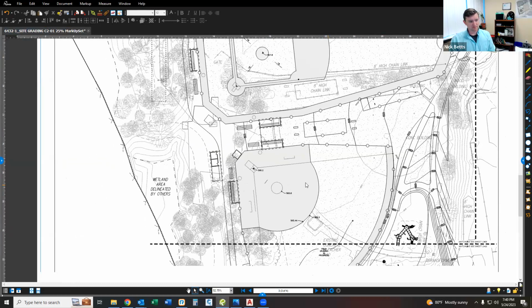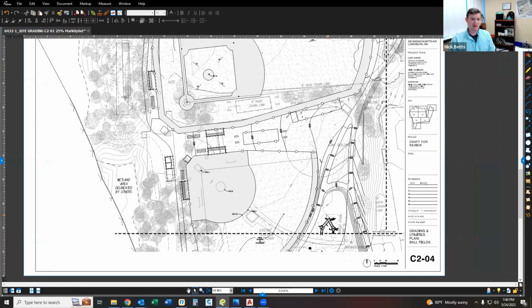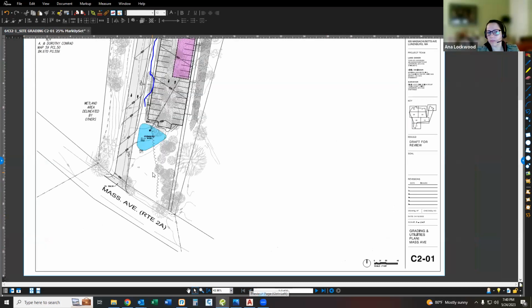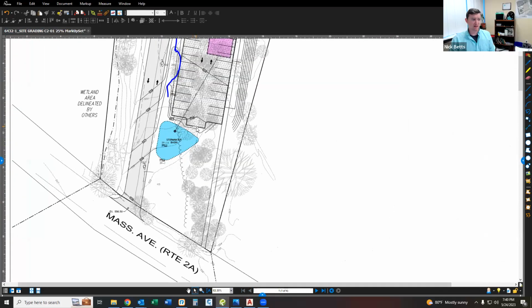What else? Did I answer enough questions about the parking area, or did you want to go back to that? And the reason, Karen's question about why can't we make this connect? I think one option was to just go straight, and the other option was to curl back, which is what we originally had. Again, you're adding impervious area, and you're taking up the space that we need for stormwater. So it's a balancing act between what I can fit, knowing that I need to capture stormwater. Every time I add 10 spaces, my basin gets bigger. So I'm actually losing more space than just what I would be giving away to the parking. It's a balancing act to make sure that you can still capture that stormwater.